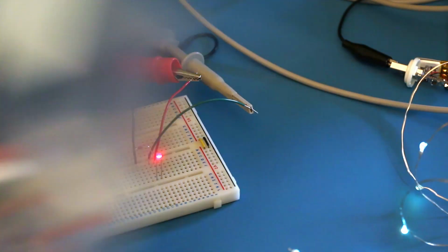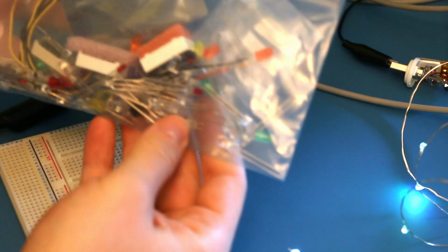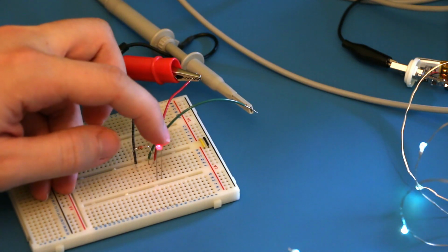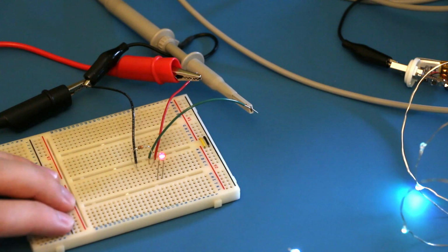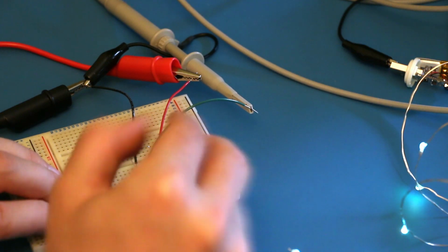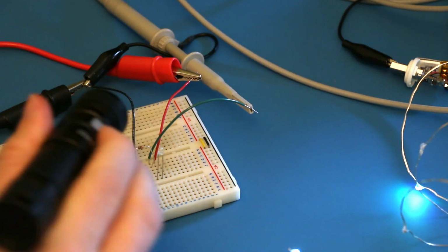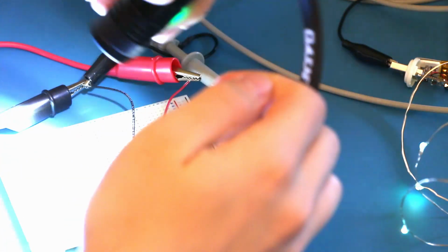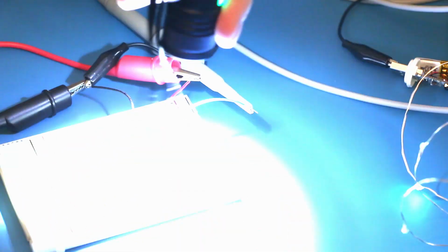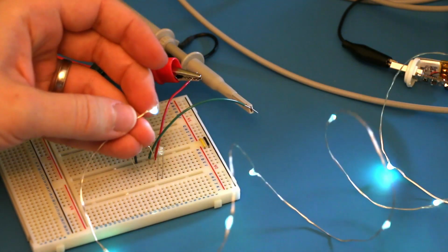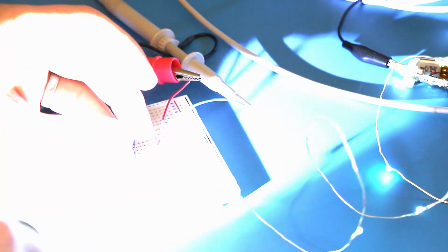Okay, I've just been through this entire bag of miscellaneous LEDs, and the best one I've located was this clear red LED. Unfortunately, even that's not good enough. If I reverse bias it and then show you the scope screen while I flash this really bright torch at it, you'll see what I mean by not having enough of a signal to work with, especially given that we're trying to see this LED, not this LED.